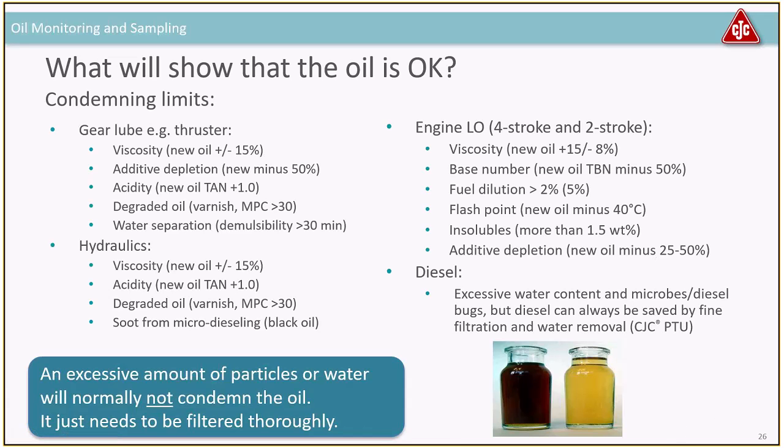And the last one, diesel. It is actually very, very seldom that you need to throw out diesel because of problems. But of course, if there are a lot of microbes and so on, you can use a filter separator to remove the microbes and the water, and filtration. I have not seen diesel that you have to discard just because it's dirty or has microbes.